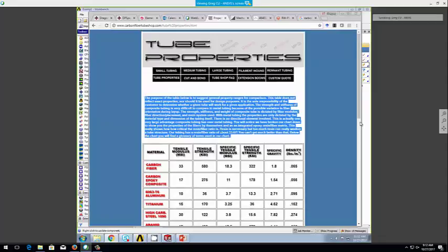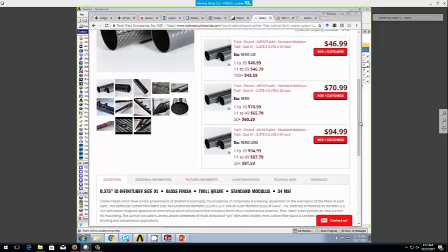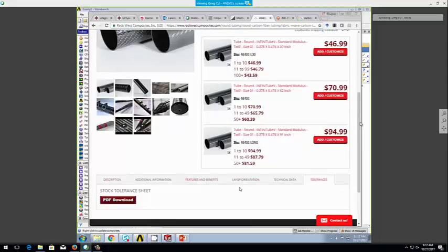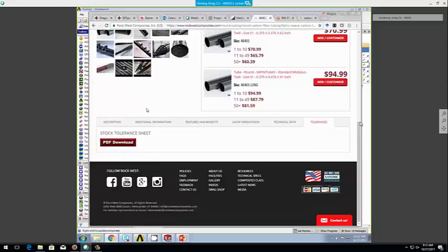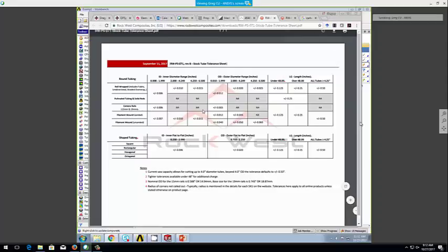It's not the death speed, but that's appropriate also for that. And on the negative side, we have the same thing. Typically, we don't pull as high loads on the negative lift as we do positive lift, but we were down watching the air races at the Indianapolis 500 track, the Red Bull air races, and they pull as many negative G's as positive G's, and they are limited to 10 G's positive, and they have an accelerometer on board, radio link to the officials, and a number of the airplanes went over 10 G's in their pull-up maneuvers, and then they pull lots of negative G's too. So we're not going to pull that many G's. I hope we won't do that.